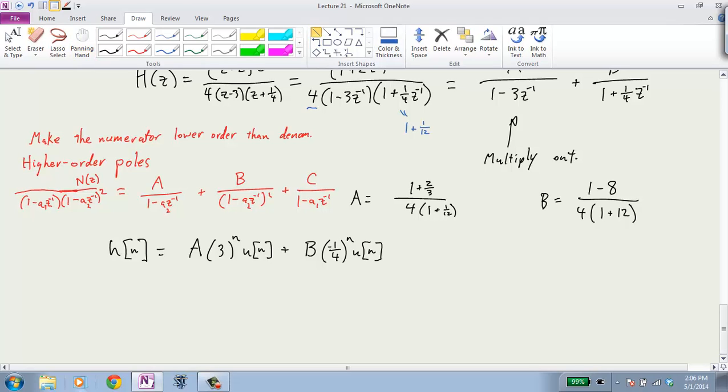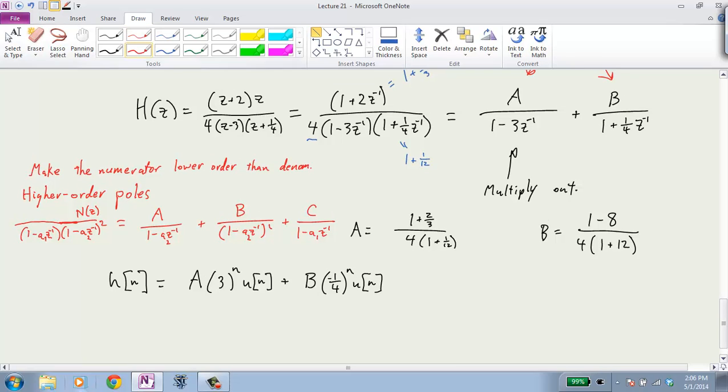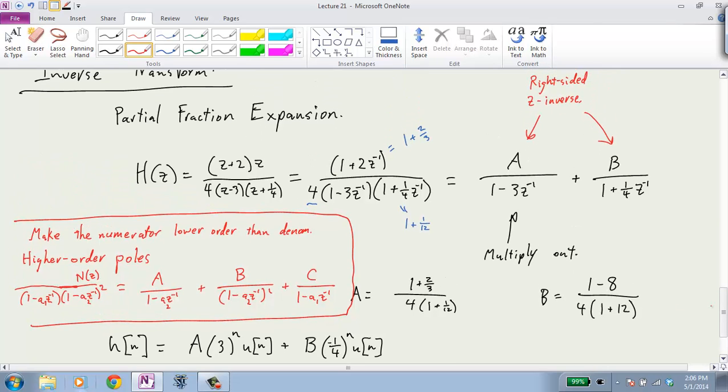Okay, so now we know how to go from a block diagram or something to the Laplace transform, or maybe from a differential equation to the Laplace transform, and then how to take that to the time domain with an inverse. Yes? Sorry, for this particular example, would it be valid to take the z transform of different pieces and then convolve them in time? Oh, because you're saying products. If you could do the convolution in time, that would be valid. That's an okay way to do it.